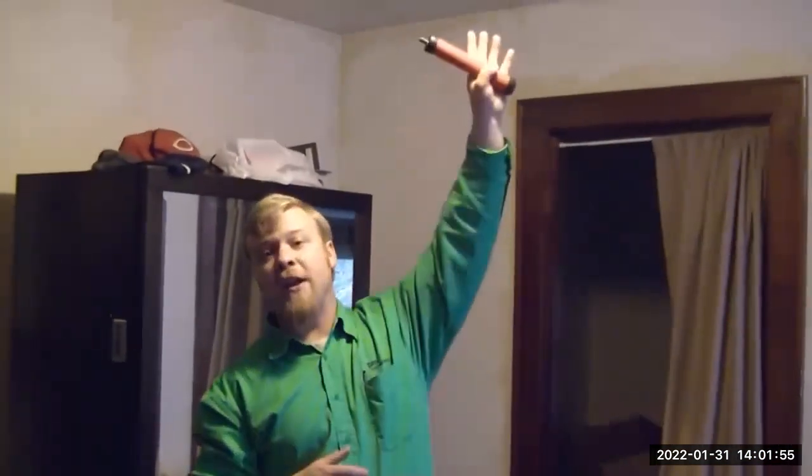Another thing that we always want to check, especially on a second story with attic space above, is any type of penetration that's going into this attic space. So we have a light here, and I'm checking it, and this one's good. It's sealed up. There's no air coming in through there, but that's a real common source for having that unconditioned cold air from the attic space come into the living space here in the bedroom.